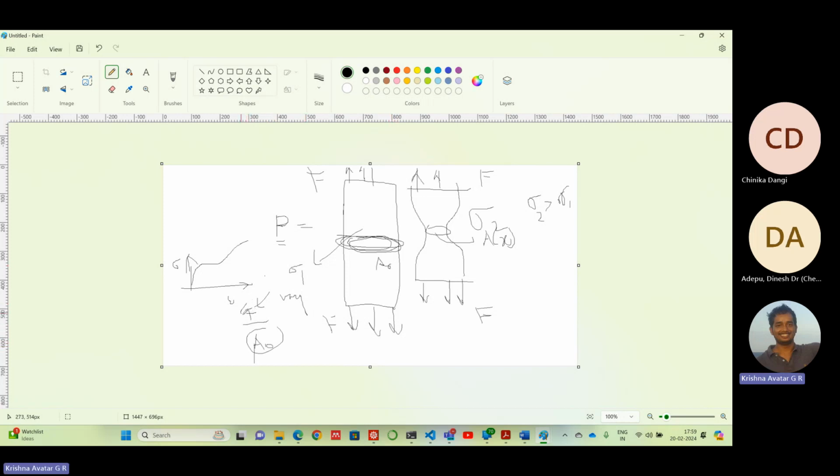So you see that although the force is in the current configuration, the area happens to be in the reference configuration. This is what we call the engineering stress. Actually, engineering stress is a very colloquial term for the first Piola-Kirchhoff stress, the first PK stress.